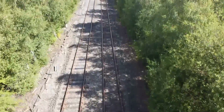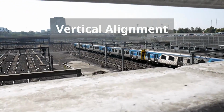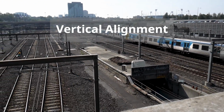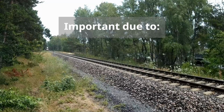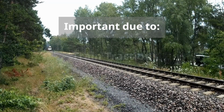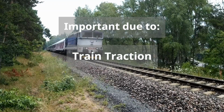As well as turning left and right, we also need to think about going up and down. This is known as the vertical profile, or vertical alignment. The world cannot be made completely flat for the railway, so trains do have to go up and down inclines. However, given their weight, especially freight trains, they are only capable of getting up inclines of a certain gradient. More traction effort is required, and this also puts further stresses on the rails, which leads to defects.